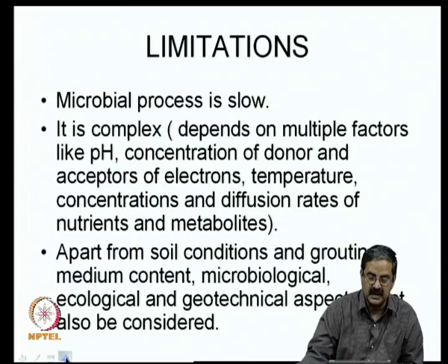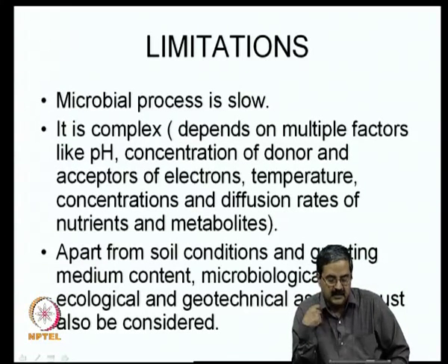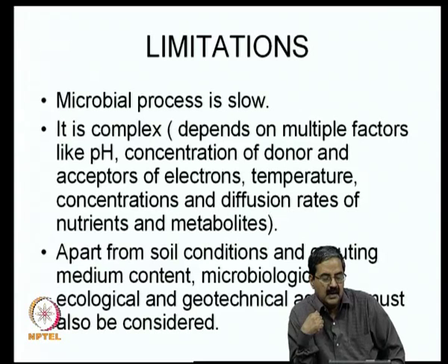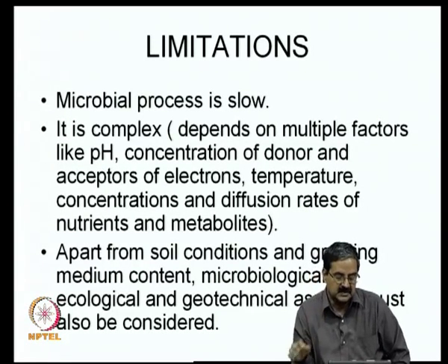These are all some applications that one can have, and one should understand that the microbiological processes are a little slow, and they depend on complex factors like pH, concentration of donors and acceptors of electrons, temperature, and diffusion rates of the nutrients and metabolites present. Apart from the soil conditions and the grouting medium content, microbiological, ecological and geotechnical aspects must also be considered.